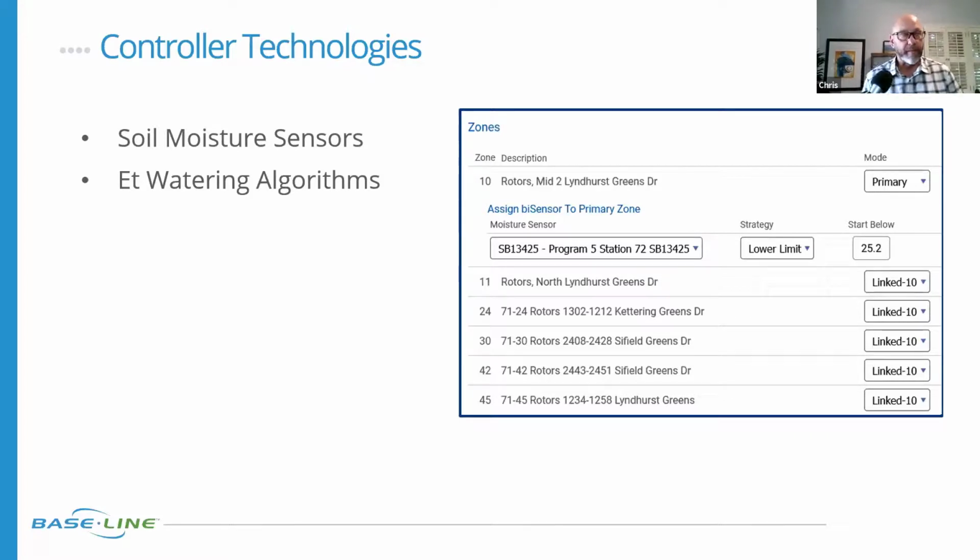I've done studies on properties here in Utah in the month of August when those monsoonal or thunderstorm conditions exist, and using the effective rainfall from those rain events, you can extend your day cycle by skipping start times that come up, because there's enough moisture in the soil profile and it doesn't require it.